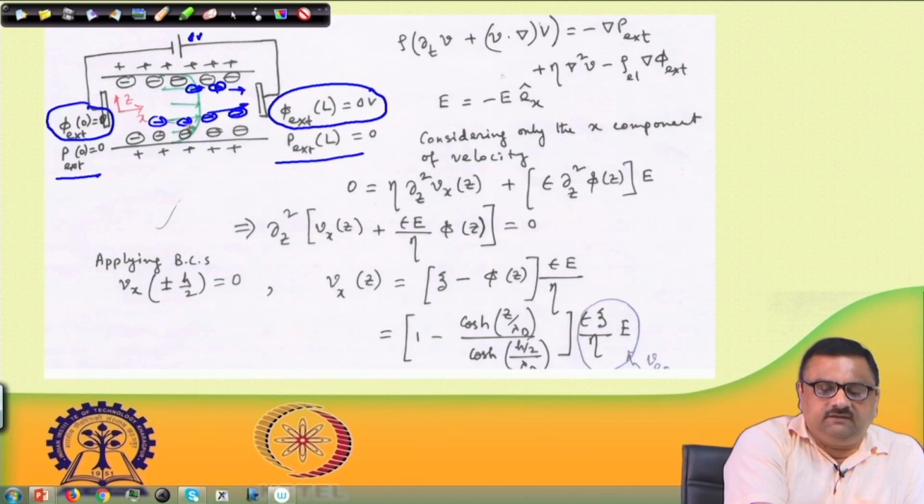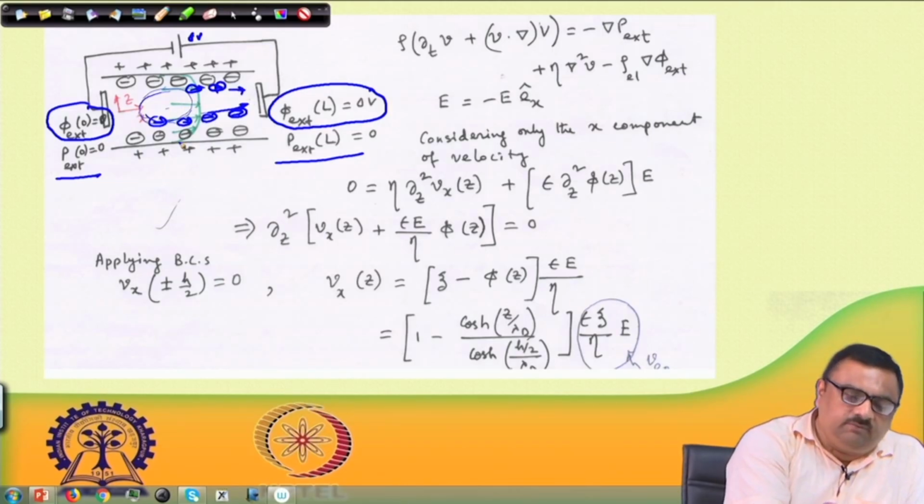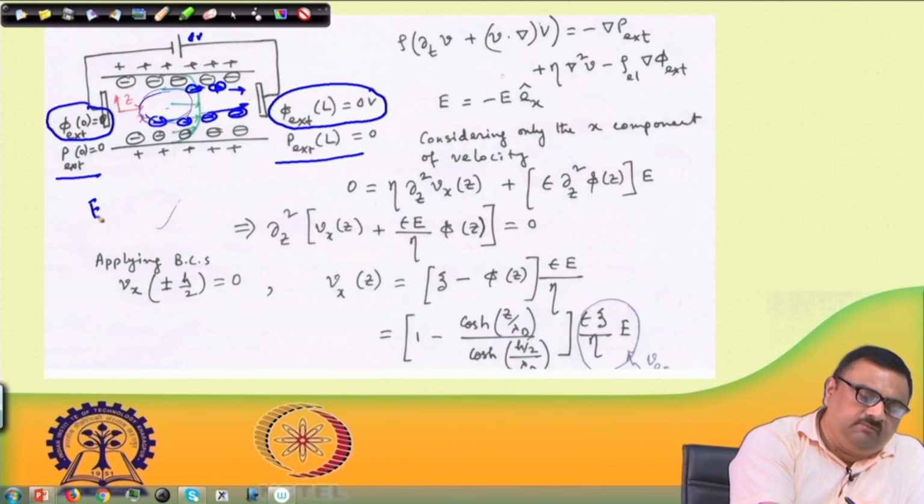Because they are pulled towards the positive electrode, they will impart a body force on the neutral fluid that is inside. So, one can see fluid continuously flowing from left to right, and this type of flow is given the name electro-osmotic flow.